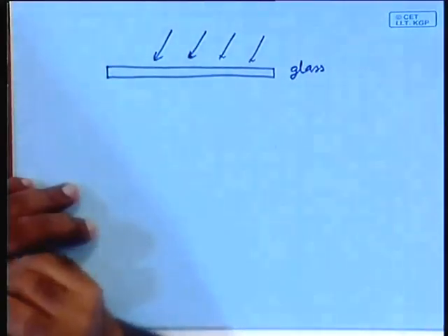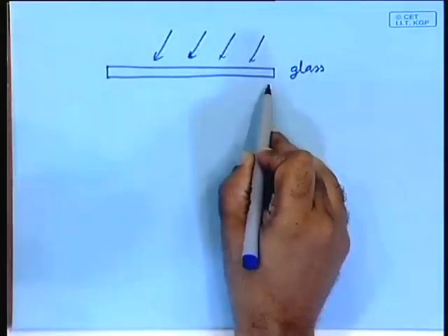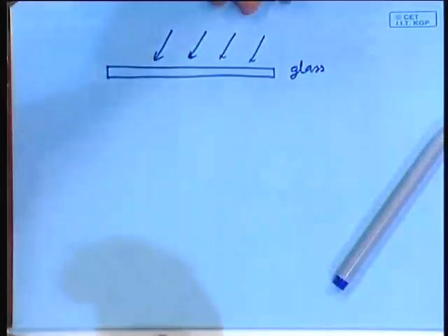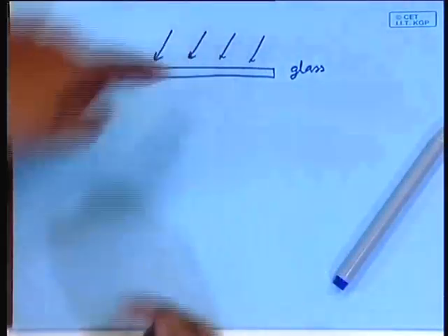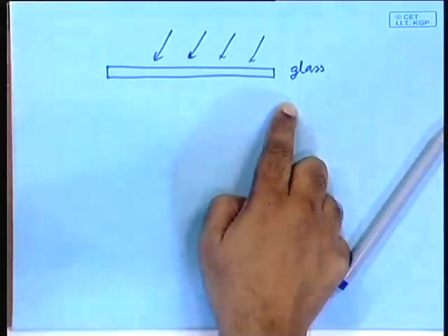First, what should go below the glass layer? Imagine the light is coming from that side through the glass into the silicon, and what did I say should go first? An anti-reflective coating, that should go first, and its refractive index should be such which satisfies that equation between glass and the silicon.